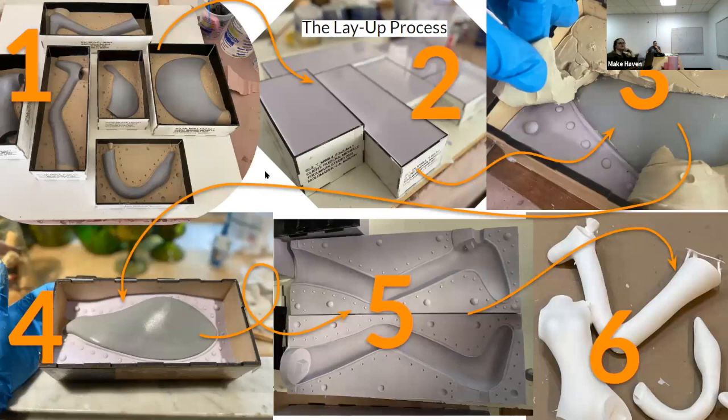This is a different kind of mold that is using a silicone rubber, and it's called a layup mold because the mold has to come apart into multiple pieces, and it was very, very important because this was a prototype. It was 3D printed, and all the parts had very precise little keys that had to go together, and so I had to make sure that the castings were going to be very, very reliable.